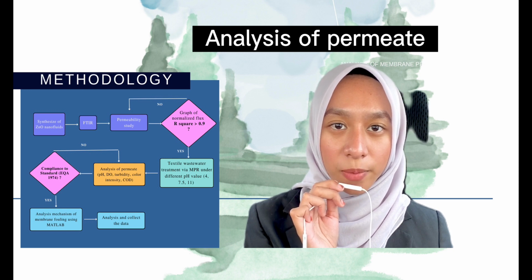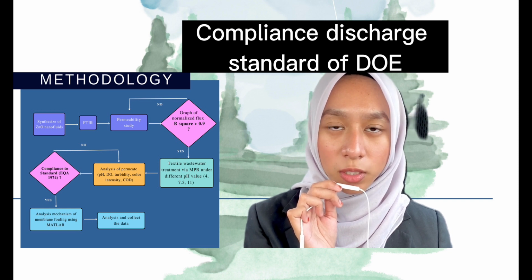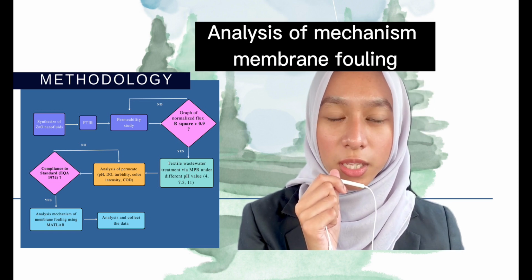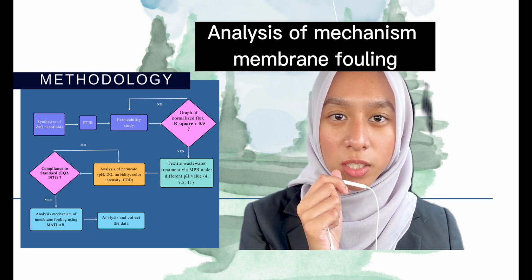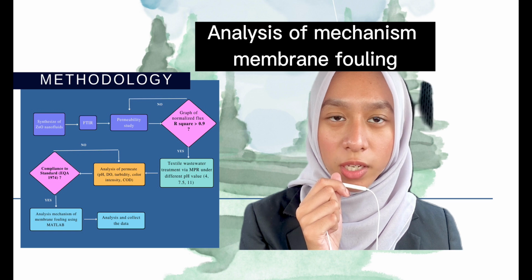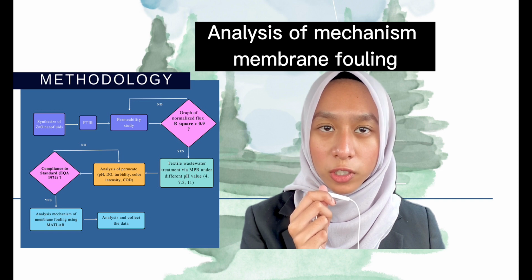intensity and COD. Then, it was compared with the discharge standard by DOE, to see whether it complies or not. From the linearized equation for each type of mechanism, the equation was simplified into y equals kx plus 1, whereas y is verified according to the fouling mechanism. With that, the fouling mechanism of the membrane was evaluated according to the theory of blocking filtration law.